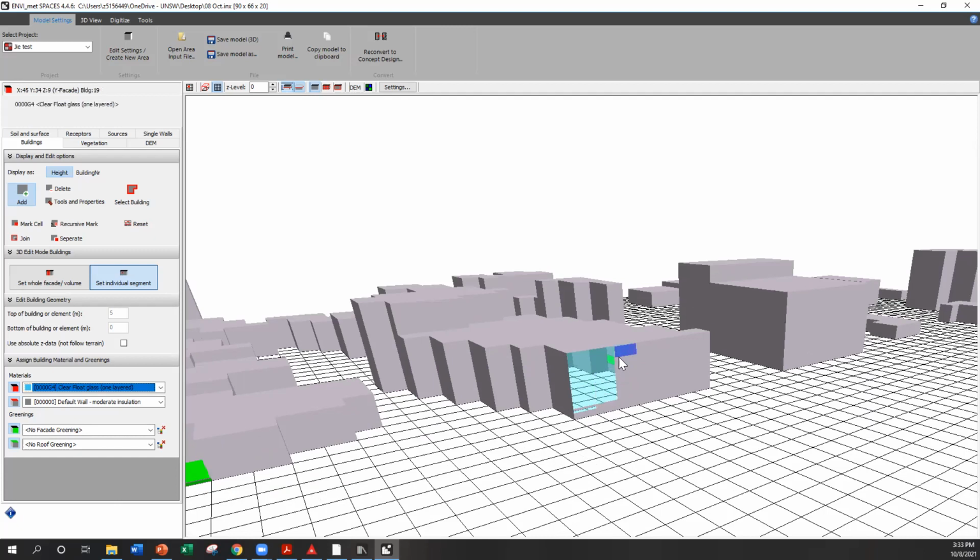Right click. Export modeling layer. Yes. If you want to set the whole surface to glazing, first select type, buildings, and you choose this option. Remember the materials, what I have said. First, allocate a fixed value. You can see at the bottom there's an assign value. It's just applied to the whole grid, maybe 10, or whatever number you want. And apply.